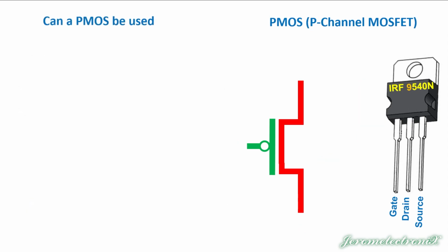All right, going back to the earlier slide, we're asking the question now, can we do the same thing with a PMOS? Can we make a NOT gate from a PMOS? Now, what we just explained about the NMOS was actually answer A on your worksheet. And so if you can remember how that all worked, you might want to fill in that truth table and demonstrate why that is a NOT gate.